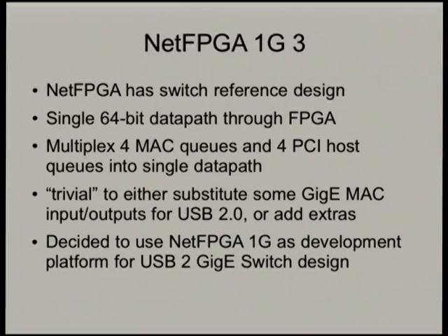The actual 64-bit data path has 8 bits of extra data attached to each data word, which tells you which channel you're talking about at any time. And the data flows through, and you can apply all kinds of filters or whatever inside the FPGA using a 125 megahertz clock. So the packets generally move through fairly quickly, and you'll start seeing data coming out the other end not long after it's arrived at the input.